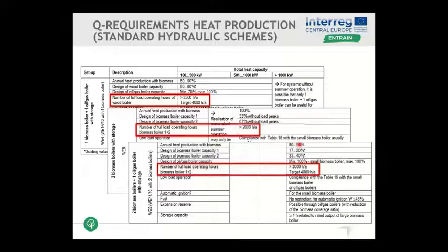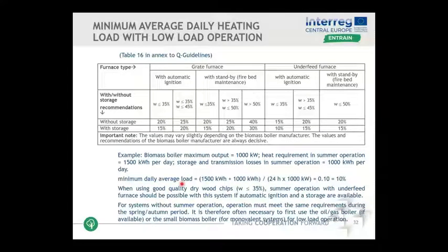If you want to increase these values, your boiler size will significantly increase. This means you get problems within the part load operation phase. So this is all about these dimensioning tables here. So we get clear benchmarks, what we want to have for the utilization of the investment, the full load operating hours. We expect that they are quite high. And of course, we say low load operation has to be in compliance with table 16, which is this table here. Okay.